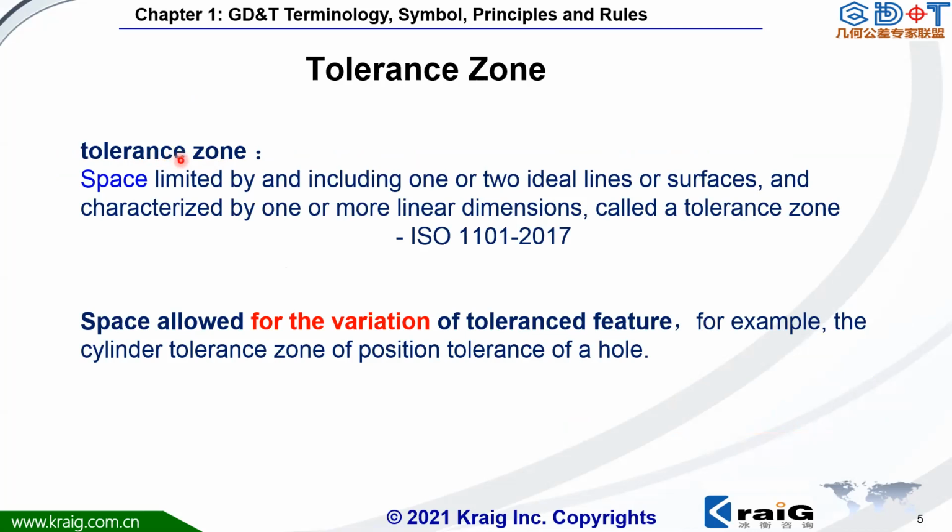Same thing here. We have tolerance zone. Zone means there's a space. Within this space, the tolerance feature is going to be limited by this space. Usually, this space is depicted or expressed by one or two ideal lines or surfaces, or sometimes it's a cylinder zone.